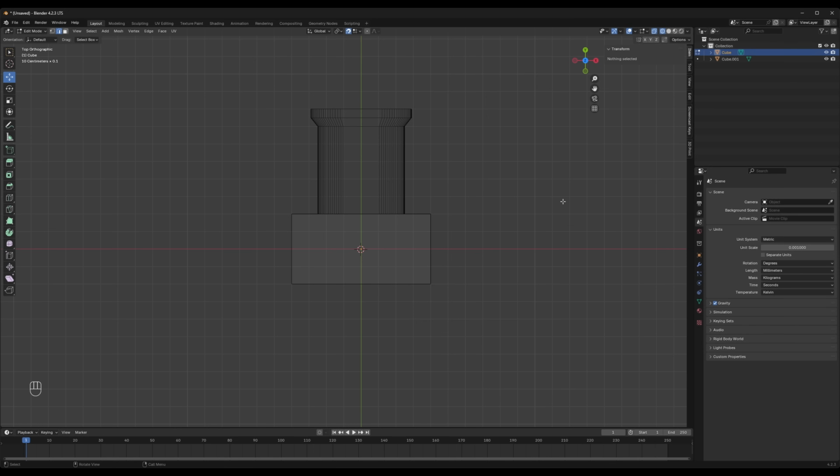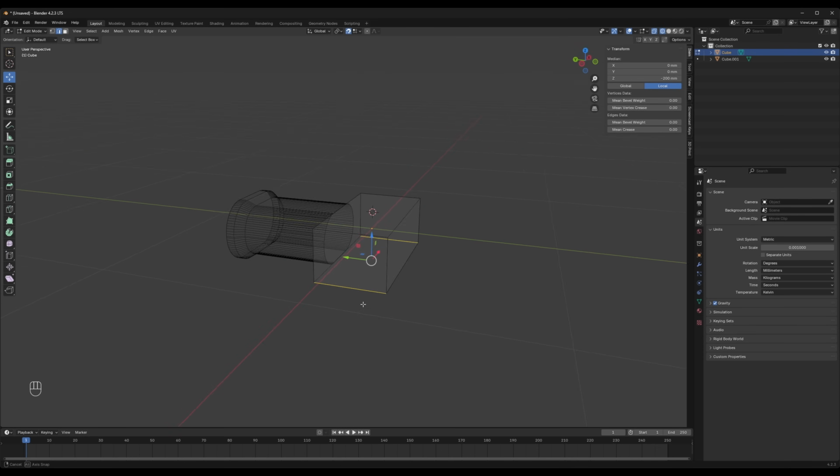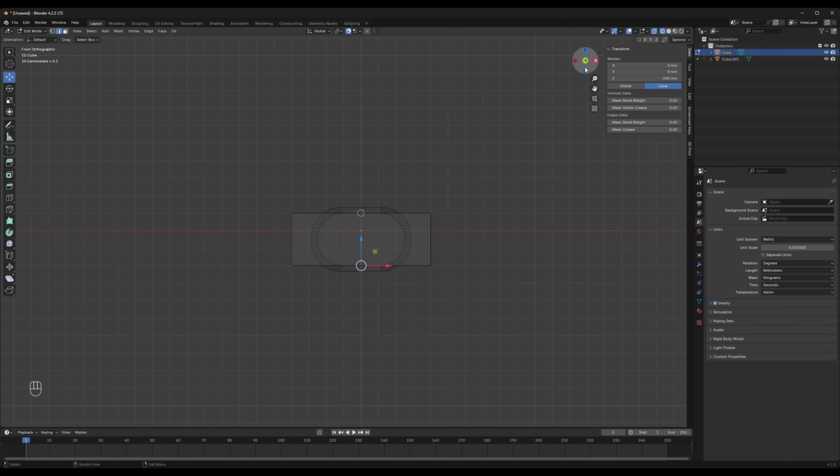Now that I've increased the width of the mounting bracket, I'm going to change my view on the axis. So I'm going back here to the -y. And what I'm going to do is drag and click these corners right here. This will select the edges of that object. So back to our Y, and then I'll hit Control B again to add another bevel. So we'll simply go right about there.